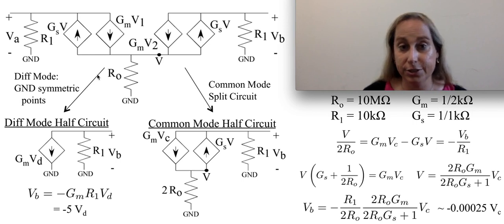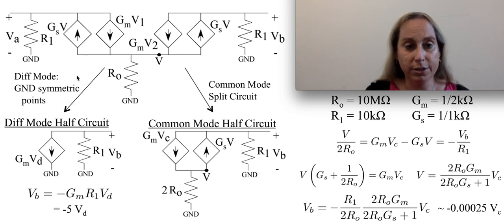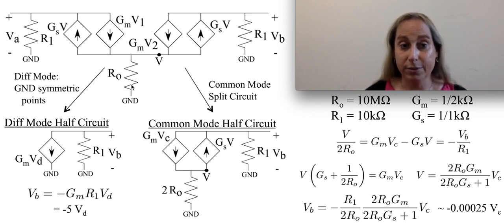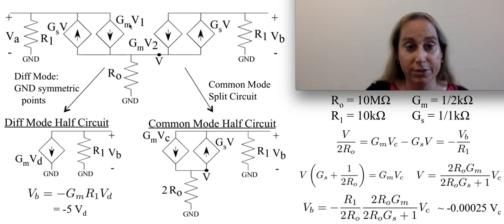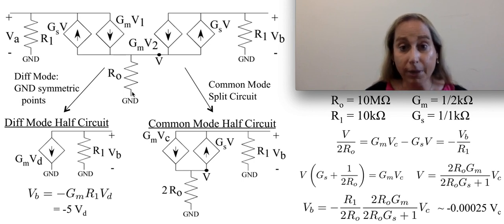So if you're looking at such a circuit and you think, I wonder what I'm going to do with this, and you think, well, where is the symmetry? Well, one of the first things you realize right off the bat is that this R0 can actually get split into two R0s, two in parallel. And that's what you get. So it does actually allow you to have a point of symmetry and cut right down through the middle of the circuit. You think, okay, that works out pretty well.